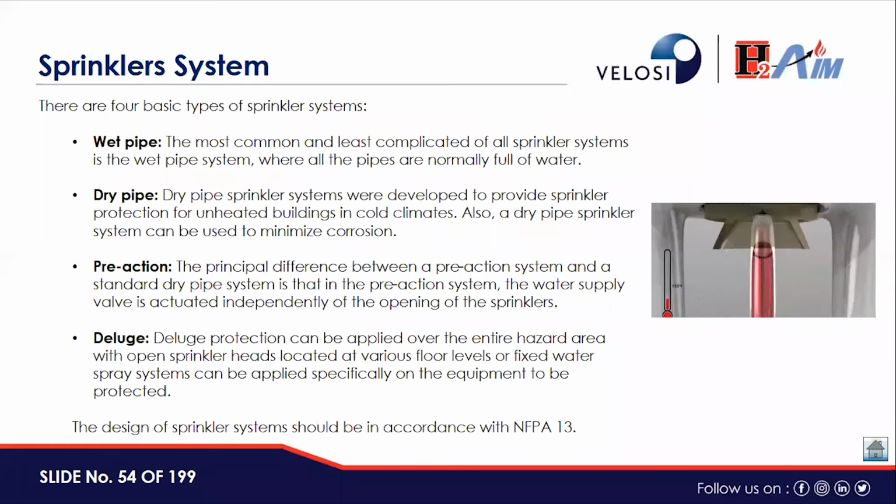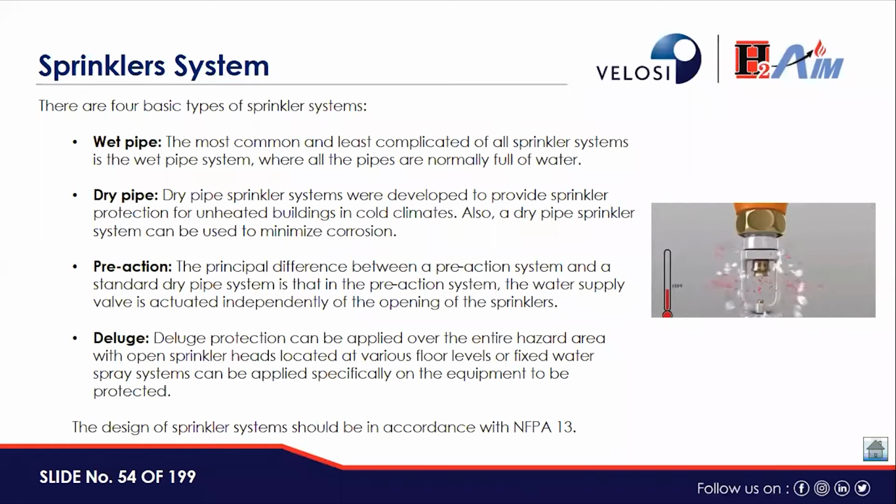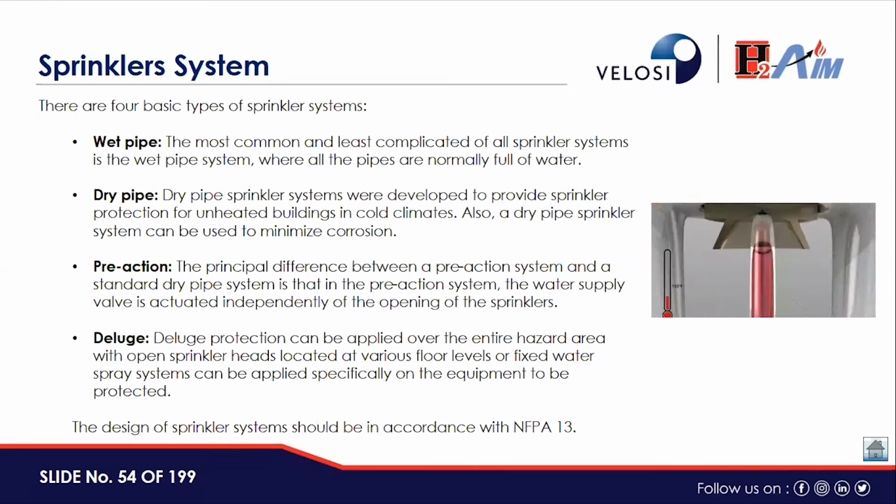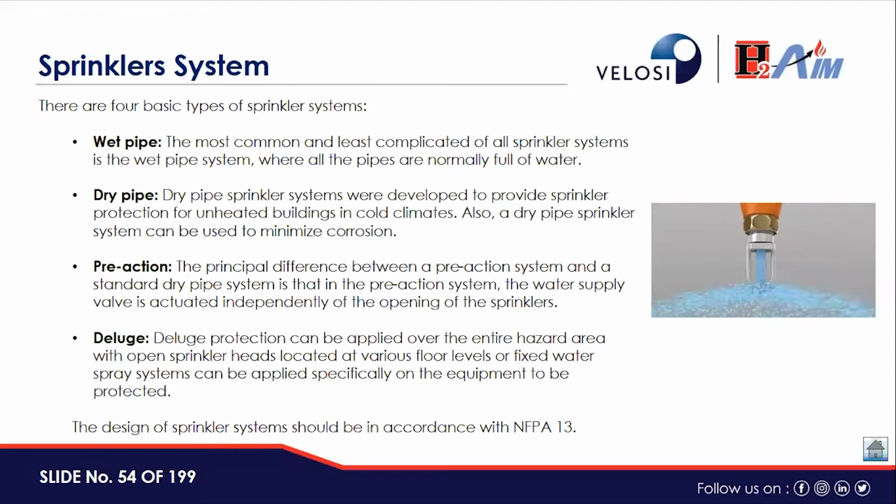Deluge protection can be applied over the entire hazard area with open sprinkler heads located at various floor levels, or fixed water spray systems can be applied, especially on the equipment to be protected. So the design of this sprinkler system should be in accordance with NFPA 13.